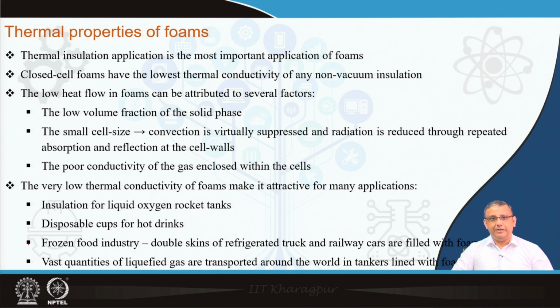the thermal insulation behavior. Now, we also learned that the foam structure can be classified as either open cell foam or closed cell foam. We also learned that open cell foams are more important for applications where transport properties are very important, for example, bioscaffold applications or sound absorption materials. Whereas, when it comes to thermal properties, the closed cell structure is the most attractive one. And closed cell foams can provide a very low thermal conductivity, and that is why they are ideal for thermal insulation materials.